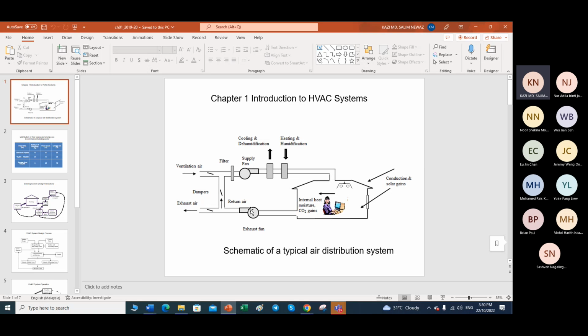After that, when it comes to the induced draft fan, its discharge will come through the damper, and how much will be exhausted will be considered from the total. That will depend on what comfortable air conditioning is to be maintained in this room area. And if 100% is exhausted when it is not required, then the consumption of power will be more there.